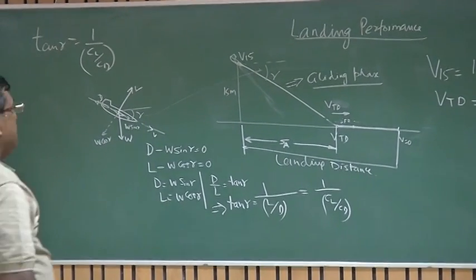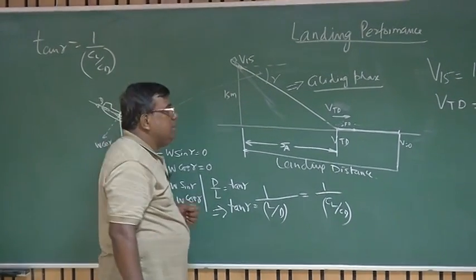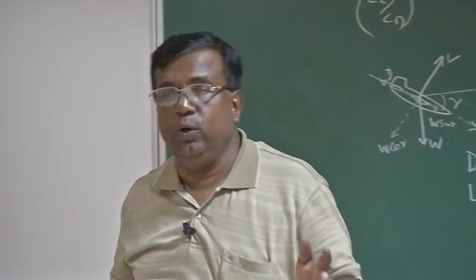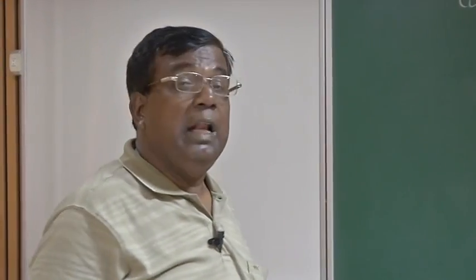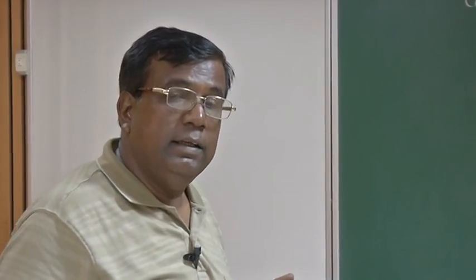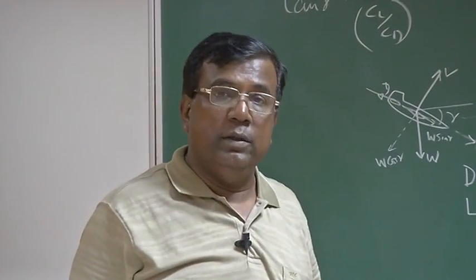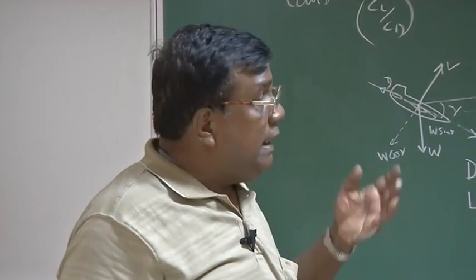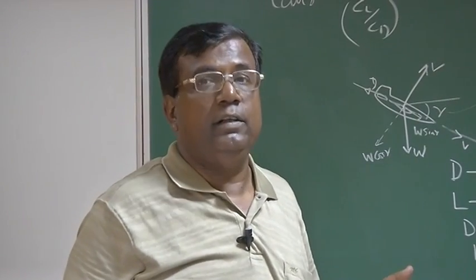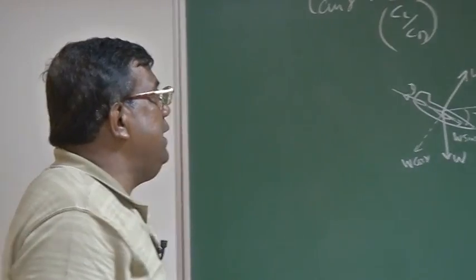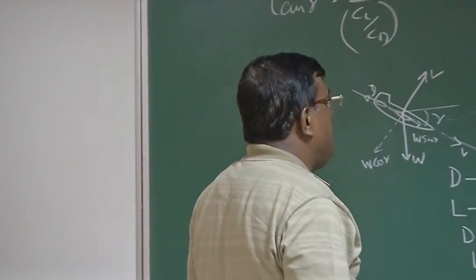Second thing, in takeoff analysis, we have taken W takeoff, complete weight, fuel, all the airplane, passengers. But when I am landing in a normal flight, I should also check how much fuel is consumed. So that time the weight is not W takeoff, it is the weight minus the fuel at least. So these finer points you should know.